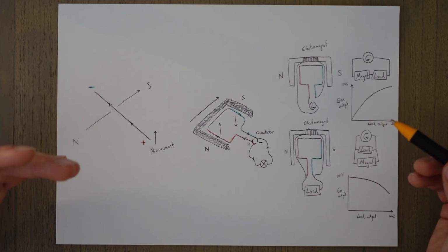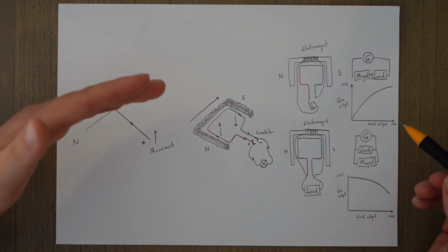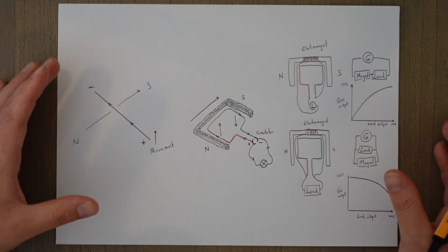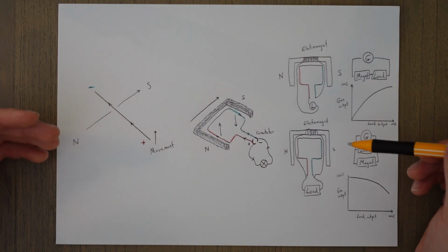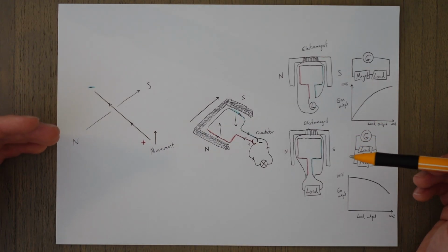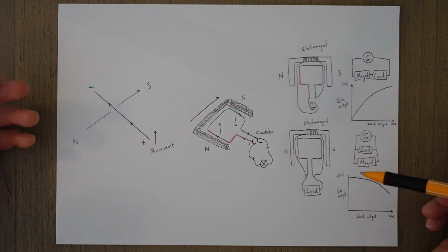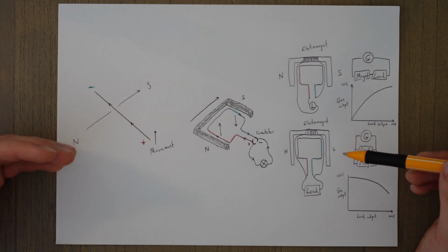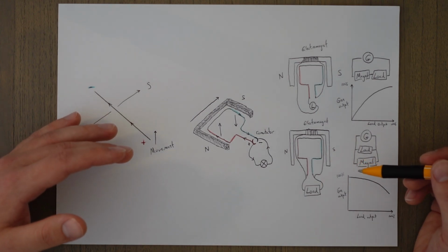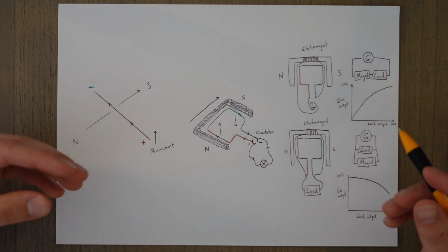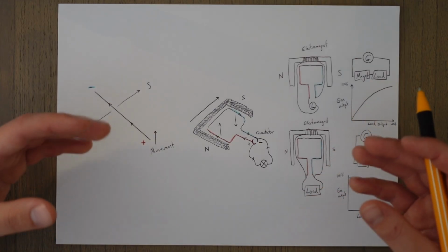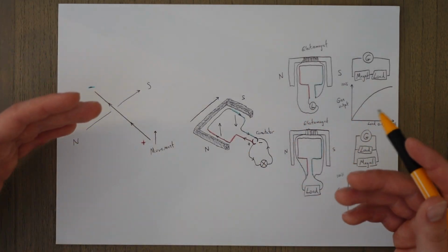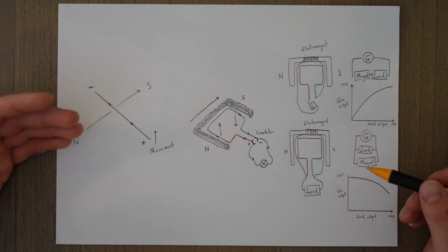Remember that the resistance in a parallel circuit is 1 over RT equals 1 over R1 plus 1 over R2, etc. And if we had a fixed output voltage from the generator, then we might see the current of this circuit shoot up to counteract for more elements and a lower resistance. Too high a current can cause a lot of damage to the circuit, and that's why we have fuses. When they experience too high a current, they blow or break the circuit and stop electricity from flowing.